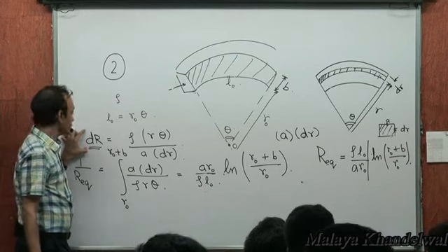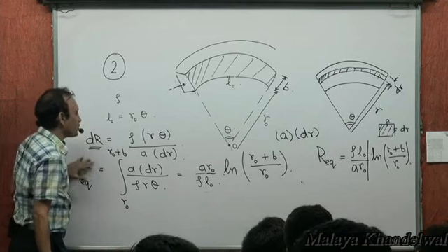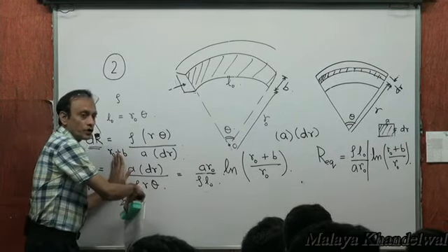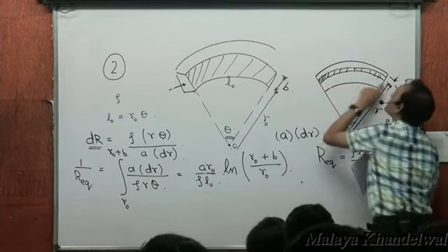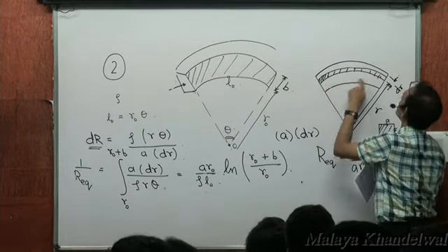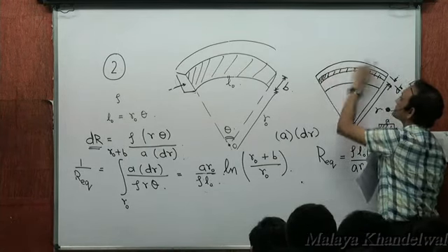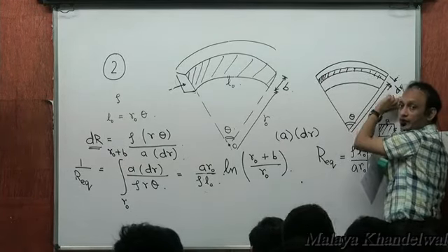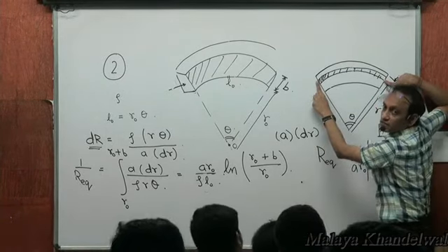That's the resistance of this chosen shaded conductor, and the reciprocal of this resistance was this. Why did I choose the reciprocal of this resistance? Because all the resistances that I encounter from R equal to R0 to R0 plus B are these concentric conductors, right? And they are connected across the same two ends.